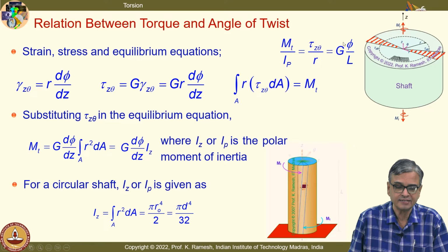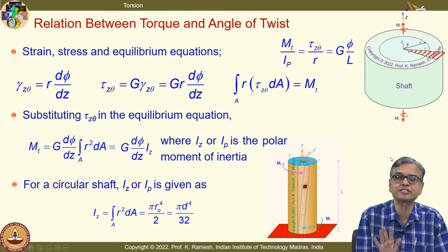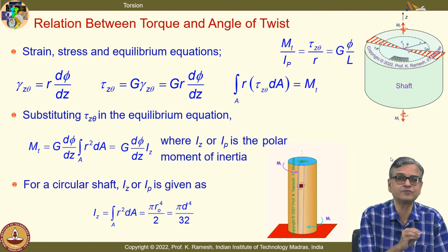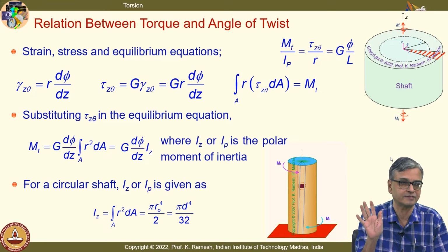And this is the celebrated equation that you have. This is developed for a circular shaft transmitting constant torque. And what we do is, when you have a twisting moment, pick out that twisting moment at that cross section, find out the torsional stress. Okay.